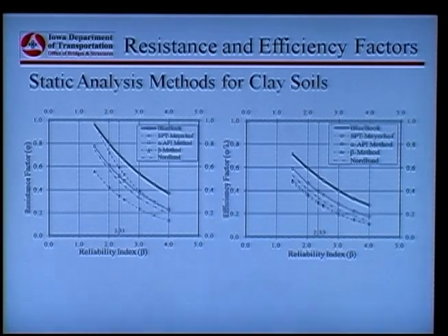This is to show you a result of the resistance factors we calculated using that complex equation, compared with a range of reliability index. All right. So as you can see, as the reliability index increases, we want to have a smaller failure region or smaller chances of failure, so we have to have smaller resistance factors.